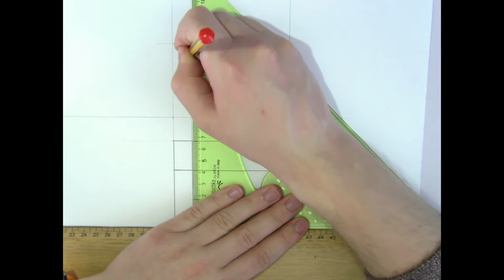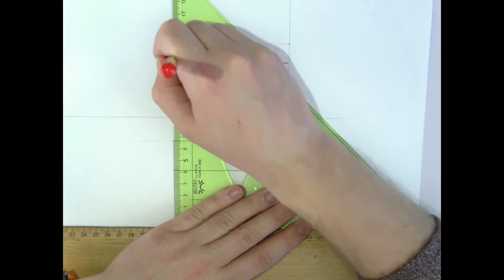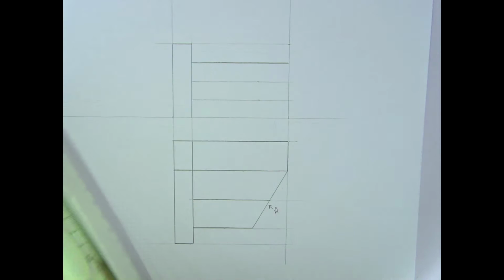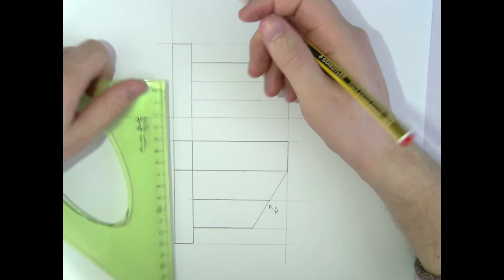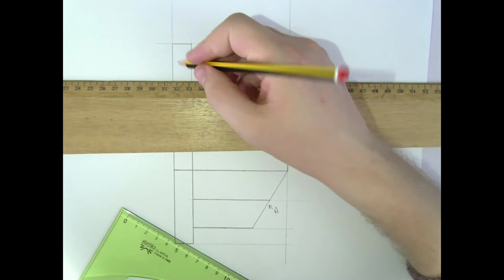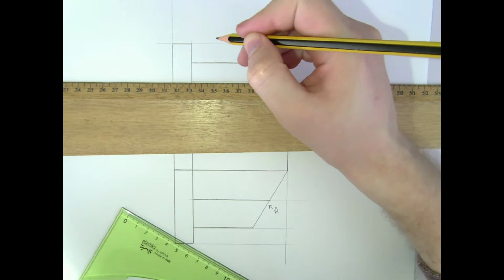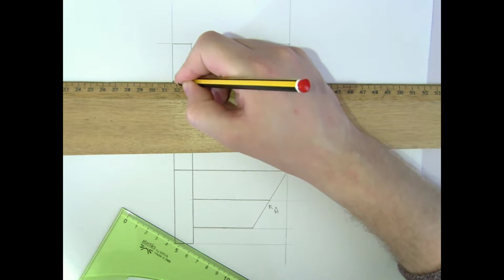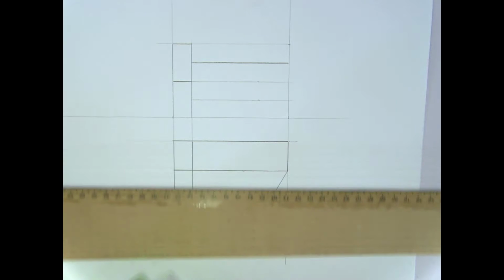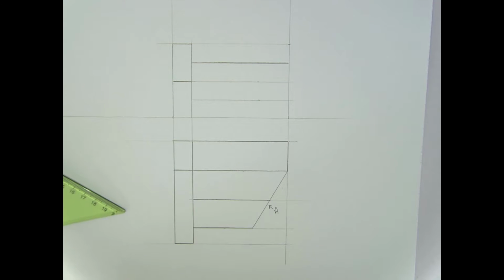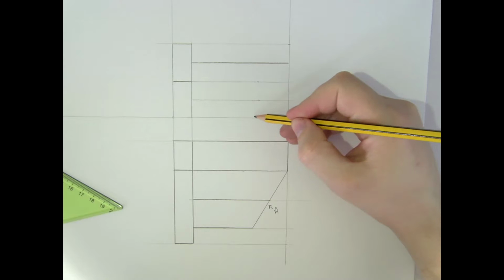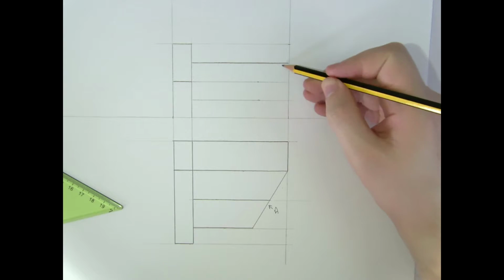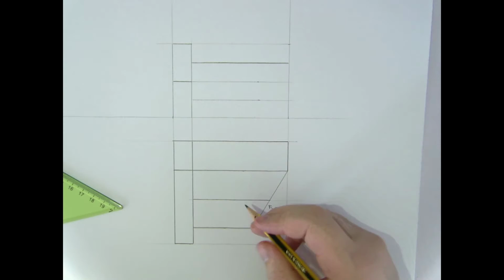Now the wall slopes down at an angle, but it does not come all the way down to the ground. There is a vertical face on the front of the wall, and that is up the same height as the second step, so it's up a height of 30. Now what needs to be done is we need to locate the steps here. So as it's sloping, they're going to be coming up this way, going back up and working their way back in that way. We need to find each of those points.